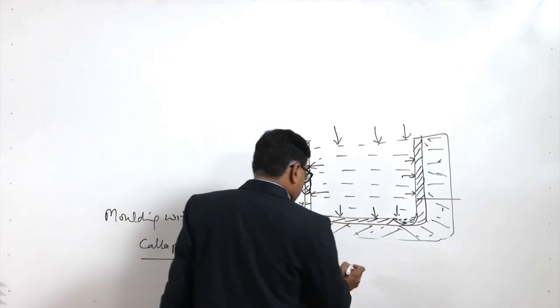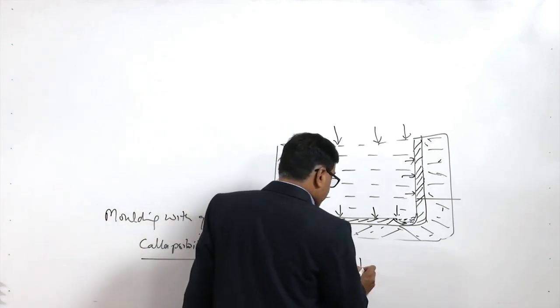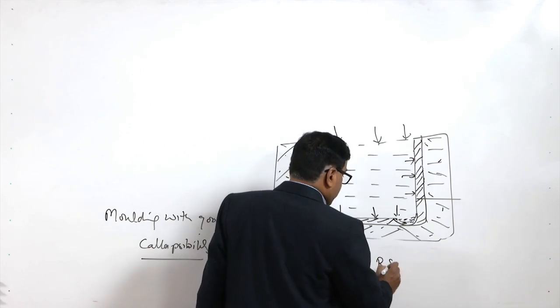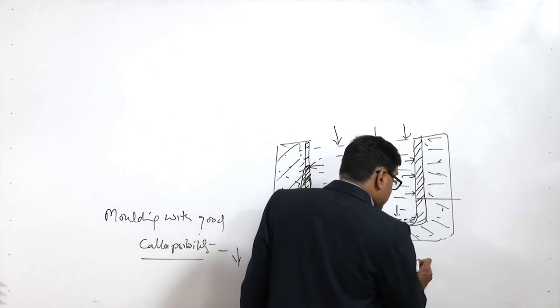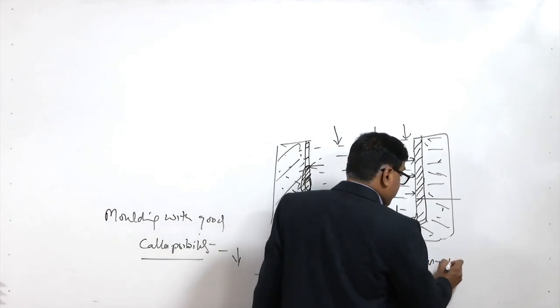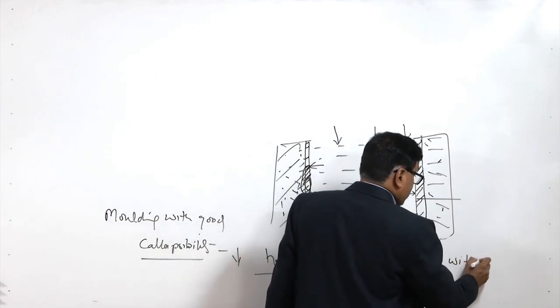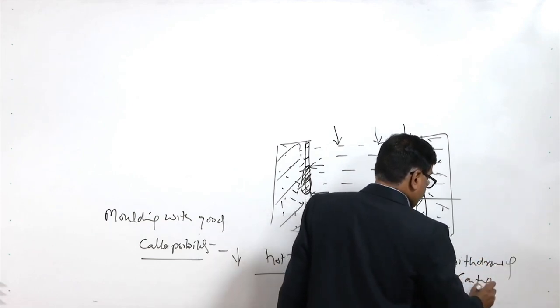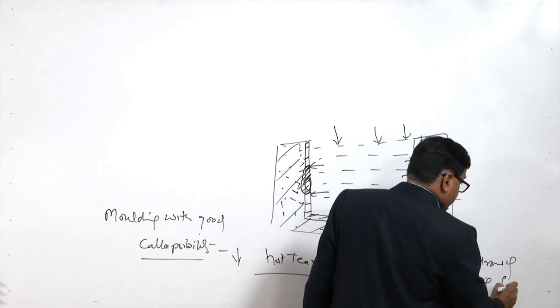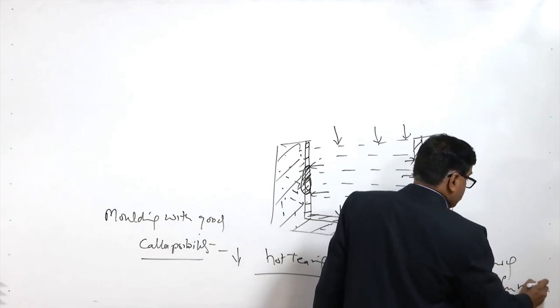It will also reduce the tendency for the development of residual stresses, and it will facilitate the easy withdrawal of the casting from the mold.